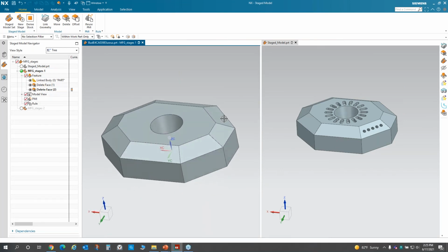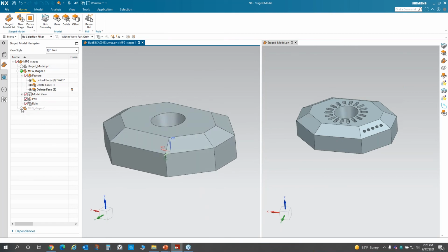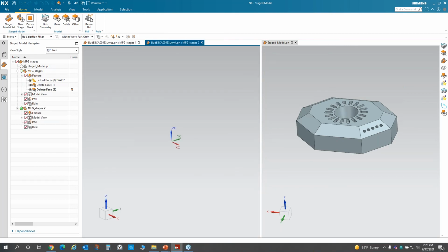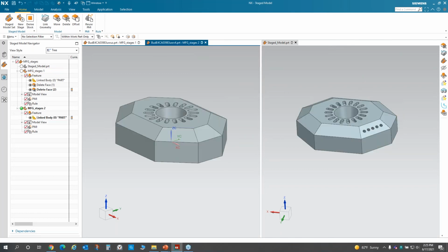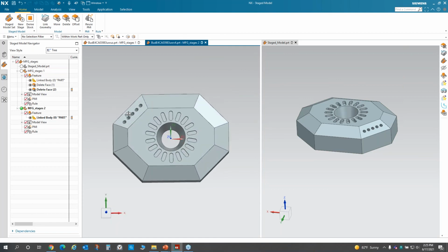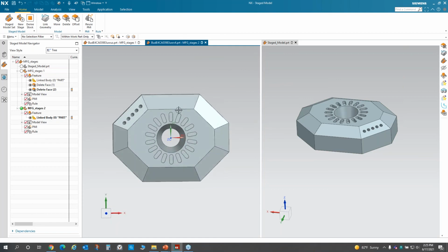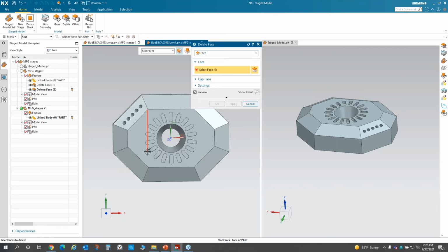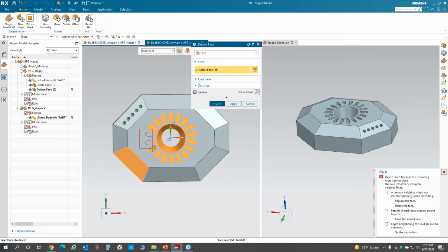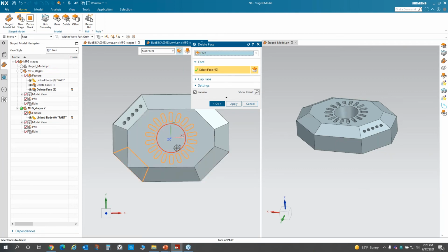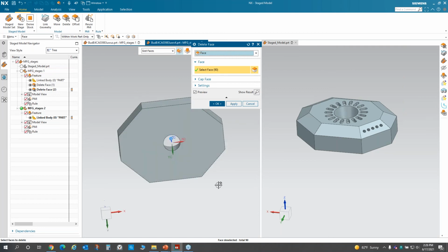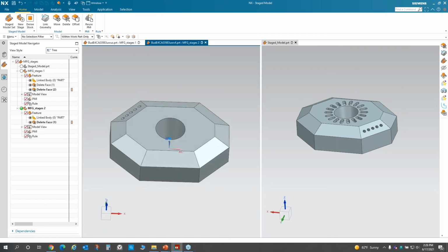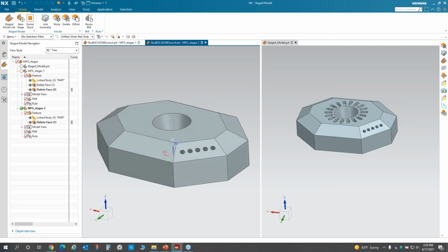So now I've got stage 1, that quick. And then for stage 2, we'll link this body also. And on this one, I'll just say the last thing we're going to put in is those slots. So that's the only thing I want to take out of this one. So I'm going to delete the slots. And then that will be my second stage.